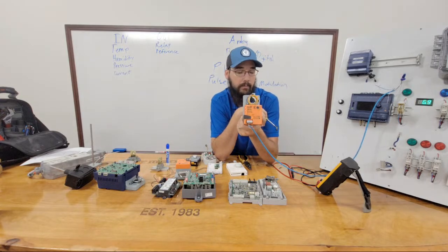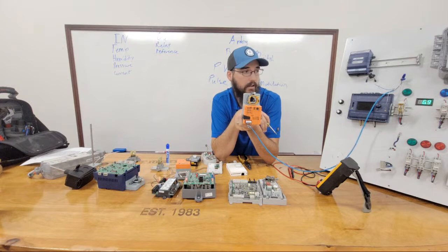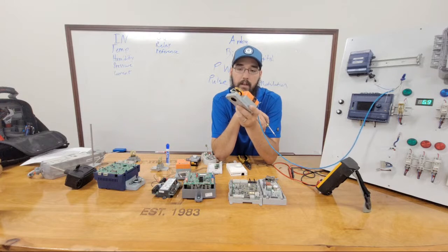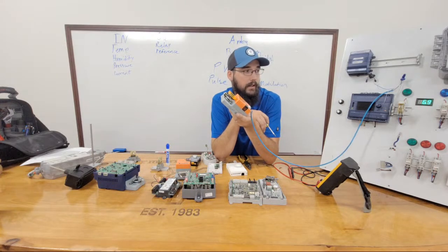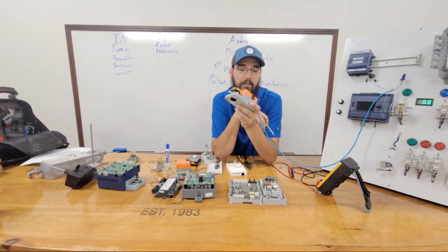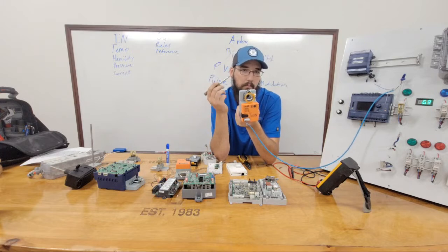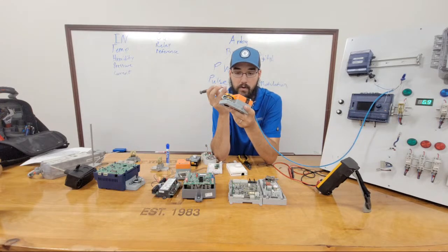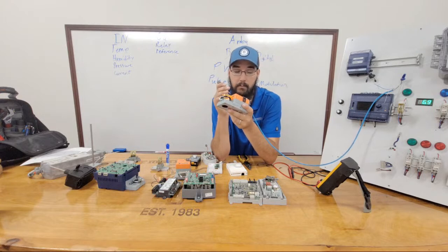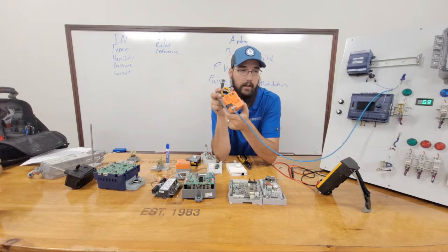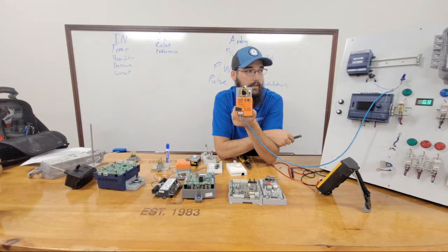My point here, though, is say you don't have easy access to the automation system, or you're just trying to figure out, okay, this is a chill water valve, and they're saying it's not working. I walk up to it, it's in a set position, and I want to see, okay, is this valve actually doing what it's supposed to do? Well, in our area, Belimo is extremely common, so more than likely it genuinely will be typically a Belimo of some kind. You can walk up and flip this little dial just as a real quick basic test.